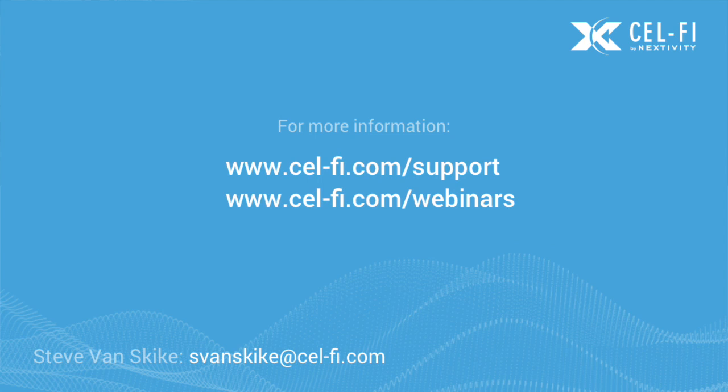Right, okay. Maybe everybody's going to come up with a different percentage, but let me take a personal stab at this. I would only probably use an Omni antenna definitely south of 20% of the time, possibly south of 15 or 10, because it's tough at a site. It doesn't mean that it won't work. It'll work great, but unless your signal to noise ratio is really poor, it's kind of a trick of perception to get your signal to noise ratio up so your customer ends up seeing more bars. Yes, that does mean a better experience, but it doesn't mean that the Omni isn't going to work.